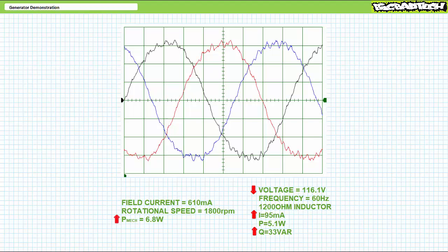Given this prime mover is operating in constant speed mode, speed remains at 1800 RPM and frequency remains at 60 Hz. Our concern in part 1 is a small reduction in voltage for this lightly loaded inductive condition. This is again to be expected, but not good, given an electrical distribution system should ideally maintain stable voltage magnitude.